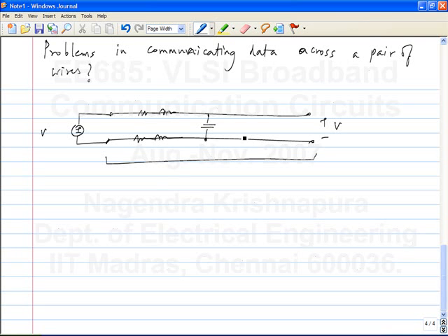It's not like you can identify some particular part as being a resistor or some other part as being an inductor, okay? And a different part as being a capacitor. The capacitor, resistor and inductor are all present continuously. So that is known as a distributed system, okay? So you can think of the wire as being made up of RLC sections like this and so on. Okay.